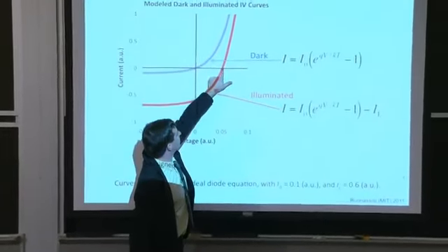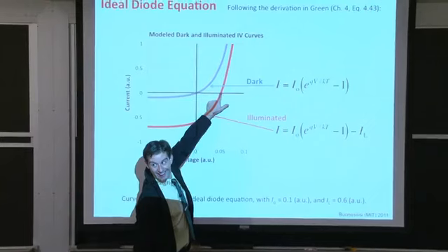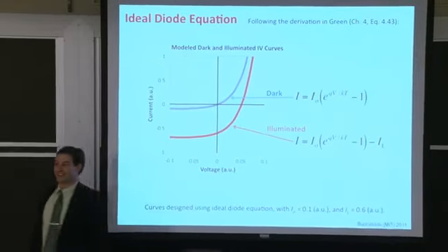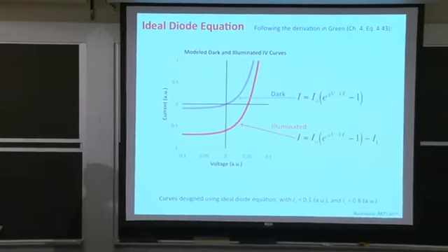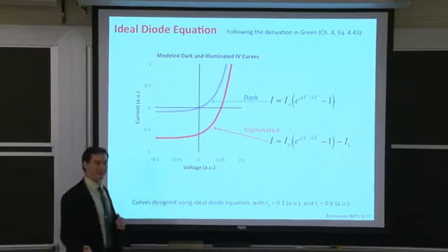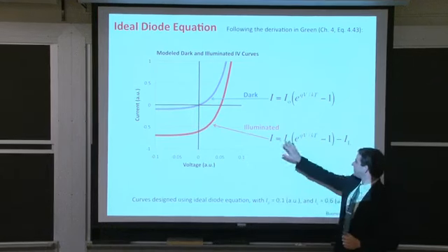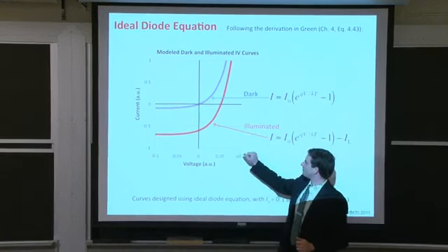What will happen to the voltage intercept right here? What is the relation between voltage and current? It's a logarithmic relation, right? So it won't necessarily be cut in half, but it'll be reduced by whatever this would be, log of 2.